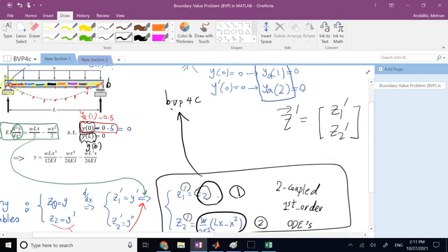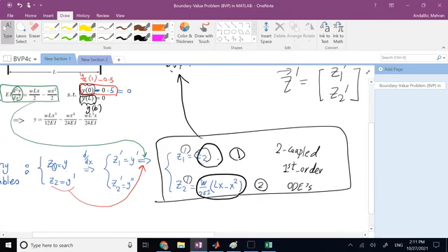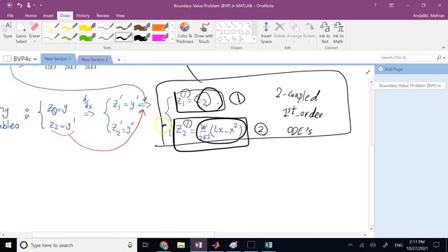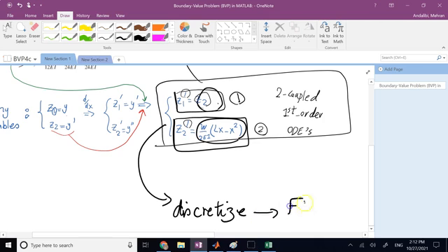So the boundary conditions are only enforced at the 2 ends, but in between you also try to minimize the error for the discretized version of these equations, because it doesn't solve these equations directly, it discretizes them into what we call finite difference equations. And in those equations, it tries to minimize the amount of error, which is the difference between the left and the right side.